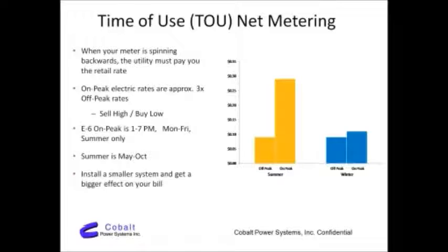And then there was another question about producing excess power. So on a daily basis, you can produce all the power you want. You can crank that meter backwards like crazy, and you build up a credit with PG&E. Now, on an annual basis, you don't want to try to go beyond a zero bill because they will pay you peanuts beyond a zero bill. It's 4 cents per kilowatt hour roughly, and that's the short answer. So typically a zero bill is sort of the sweet spot.